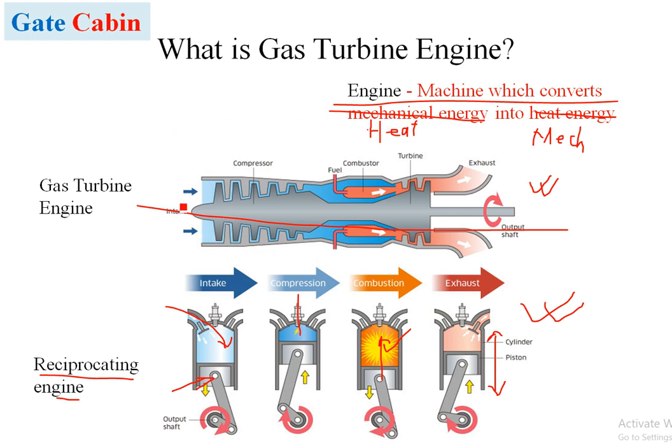Here you can see the 4 basic components of a gas turbine engine. First there will be the intake. So when an aeroplane is moving in the left direction, the role of the intake of a gas turbine engine is to allow as much air as possible, the maximum amount of air, through this small-area section. And because you are moving at a very high speed, a large amount of mass is going to enter into this intake.